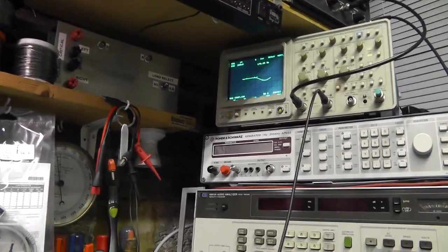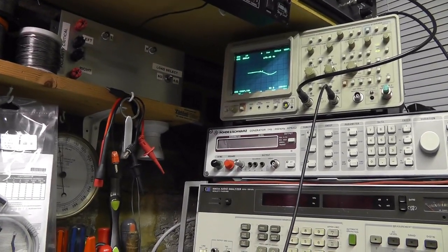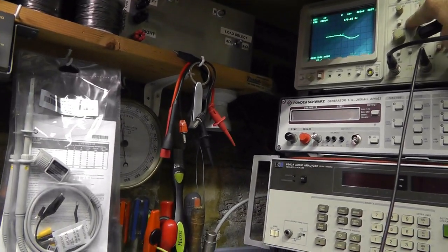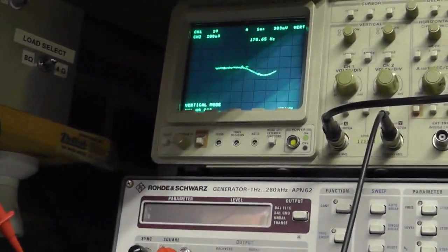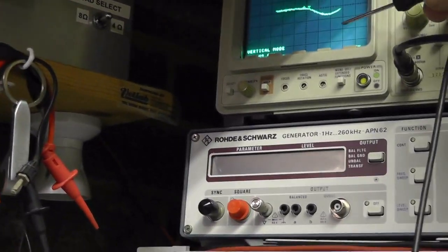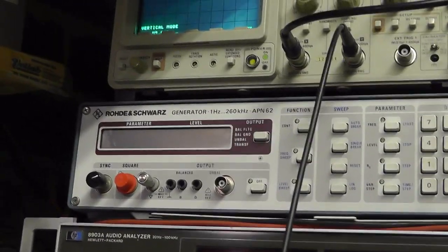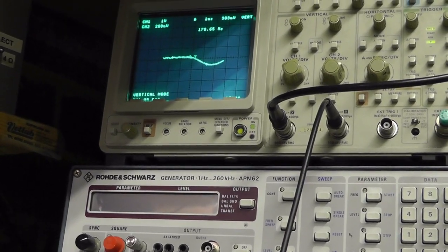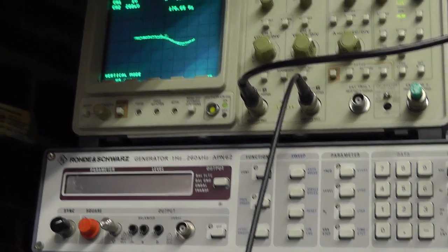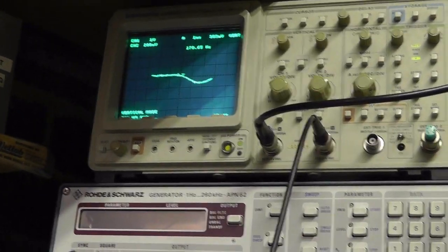Now, that scope, what we're looking at is the center frequency. We're looking at the S curve because you're in XY mode. Scope's in XY mode at the moment. So basically, we're looking at the center point is 0. Anything positive is one way, and anything negative is the other way. So we're either side of the detector. So we're going positive and negative through the detector as the sweep passes through.